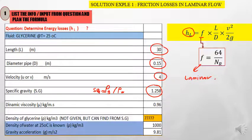And lastly, the dynamic viscosity, which is the viscosity of the glycerin. The density of glycerin is not given, but you can get it from this information. The gravity acceleration G is 9.81, and the density of water, we know, is 1000. Why do we need this? Because we are going to substitute it here, so that we will get the density of glycerin.